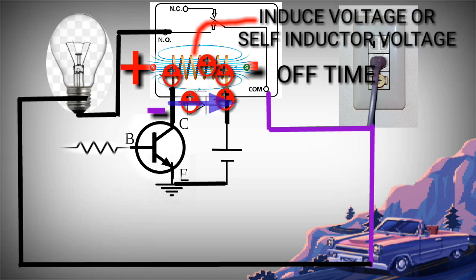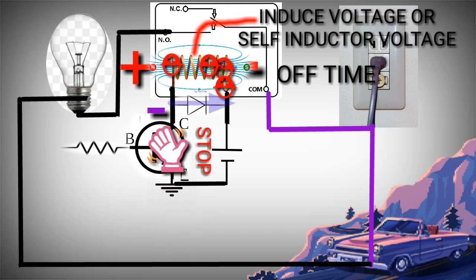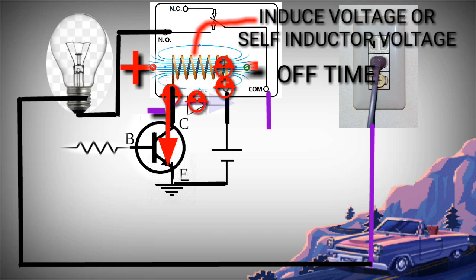Then the transistor will be protected by the diode simply because the current flows through the diode and back to the negative side of the coil instead of going to the collector of the transistor, until the magnetic field collapses and disappears.